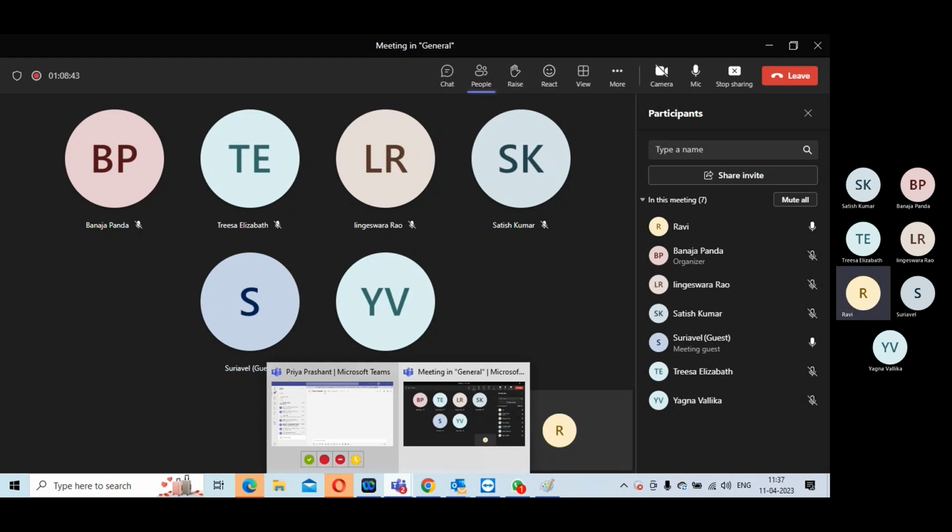That means you have to move that module somewhere. Your floor plan is all about your module placement. Getting the module placement right, in terms of congestion, timing, and clock balance. These are three key aspects. Congestion and timing are the most critical, and clock balance is the other stuff. Routability is part of the congestion.